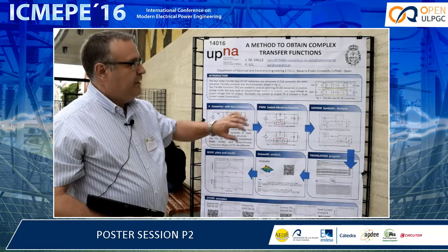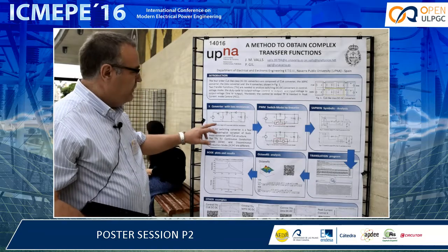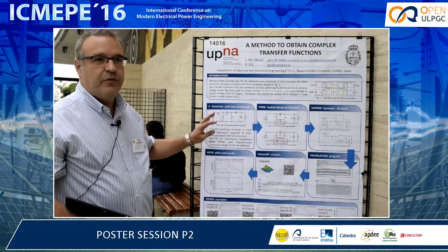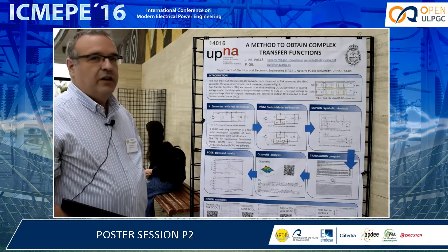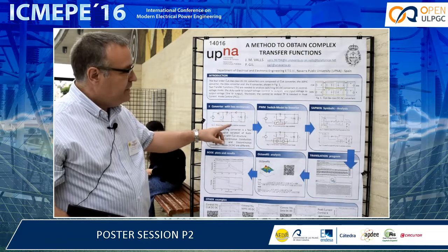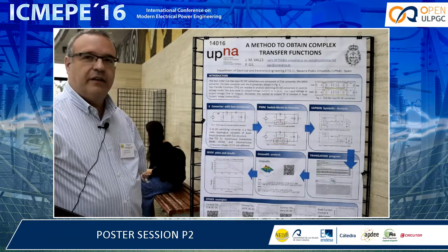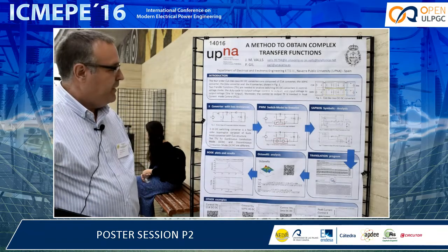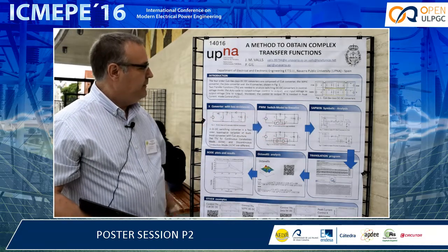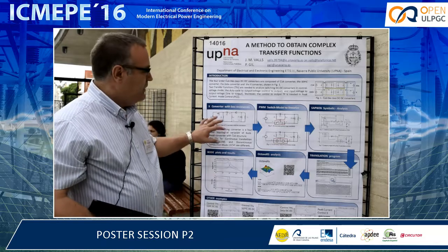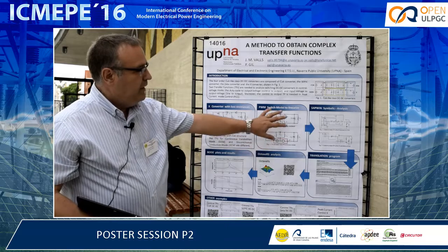When you have this circuit, you have 4 energy storage elements. You have a transfer function of fourth order, and if you add the loss resistances, you have very complex mathematics, very complex algebra. The first step is to linearize the circuit, because this circuit is bilinear, non-linear. You need to linearize it to apply SAPWIN.